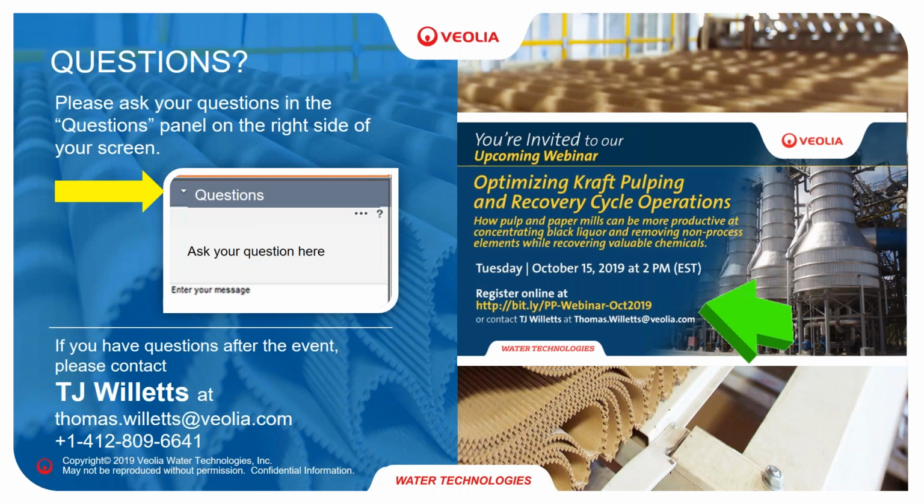Yes, we've been working with it, and Legionella, of course, has been a big thing in Scandinavia for quite a few years now. Not that we've seen so much problem from it, but when you analyze Legionella, you find it in many treatment plants. And what we have done in some cases when you really wanted to avoid it was to operate the MBBR thermophilically, because then you will kill Legionella.